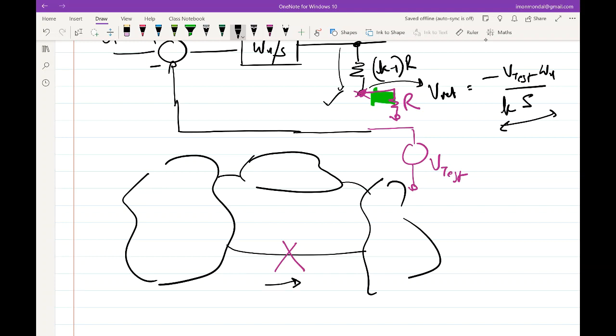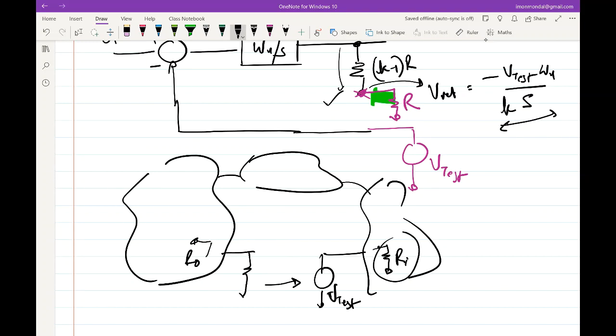Let's assume it's unilateral, and let's assume that the input impedance looking here is Ri, and the output impedance looking here is R0. And I want to break it at the location I have shown. Then firstly, obviously, I have to break it and apply a test voltage. But I have to ensure that the loading of the return side is maintained. Which means I have to translate this R0, Ri here. Then I go around the loop and do whatever I want to do.